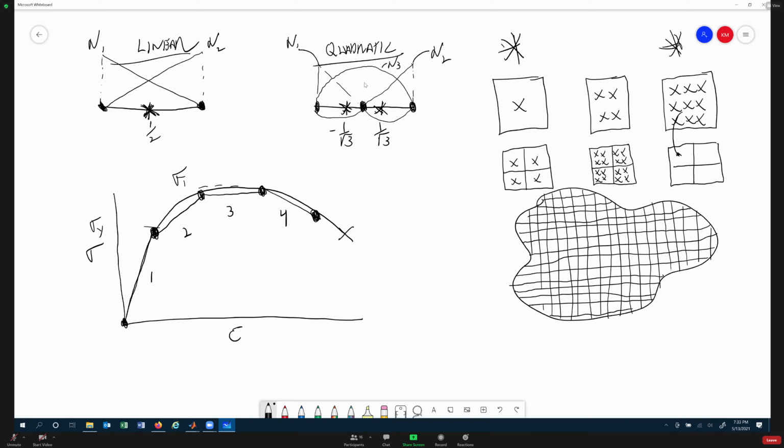So if you're designing a belt buckle or something, and you have 2 million elements in your belt buckle, and you're like, yeah, I'm the cool guy, I'm going to use this 9x9 or this 3x3 Gaussian rule to solve my belt buckle. You're going to be waiting a really long time for results, right? You're using ANSYS at school. It's not going to work. There's going to be too many elements, and you're going to crash it. And if you're using it at work, you're probably going to get fired for using computer power that long for something stupid.